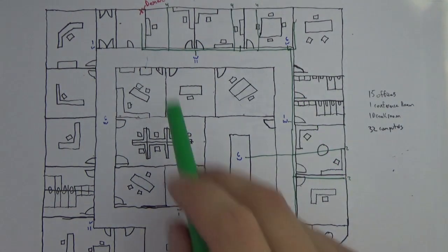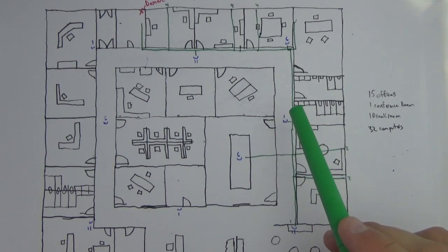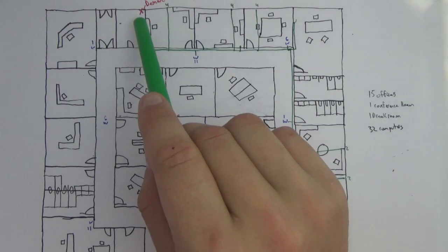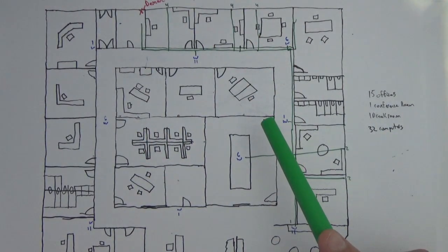We're going to label the cables. This is critical. As we're running each of those lines, we need to label them so that we know which cable is which. We're going to terminate the cables in the comm room. We're going to terminate the cables at the keystone jacks, the service locations, and then we're going to test them. And we're going to plug in a tester.